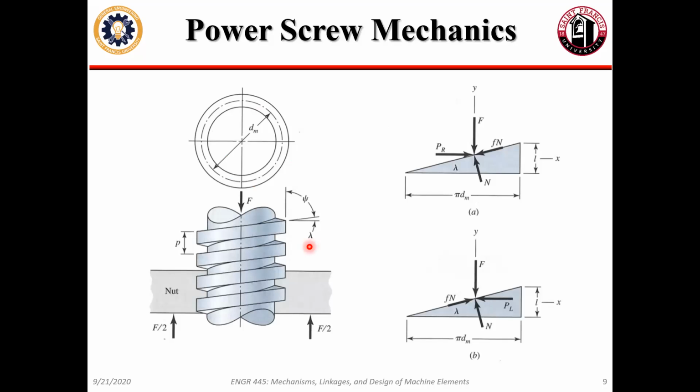That lead angle is also directly, if I take a slice out of this screw and look at it from just one side, like these wedges here. That lead angle is the slope of my wedge. It's the slope of my thread. So you might imagine the top surface of this wedge being the top surface of my thread here. The point of this wedge is just the starting point of the thread down here. I just draw a line across and up, and that's the rest of this wedge. All right, does that make sense?